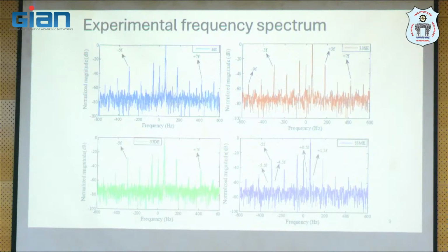This is a lab grade motor, assembled by graduate students working for research purposes. So the assembling techniques might not be very good, right? Probably when we assembled it as a healthy motor, we introduced a higher degree of eccentricity. There is no way to verify that. So these are things that can impact motor current signature analysis. Another aspect is voltage unbalance and voltage harmonics, which can also have an impact.